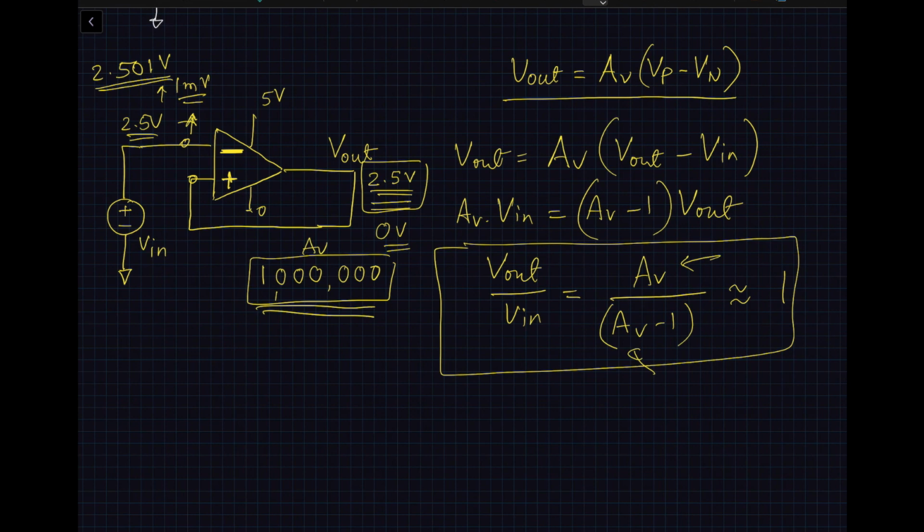And the positive feedback generally, in the amplification type of situation, is not a good thing, because it would latch up the system one way or the other. And in the speaker and microphone example that I gave you, it won't latch up. You will just hear a really loud tone, which is the other mode of operation of the amplifier, which is like an oscillator. Okay, we are going to touch upon that later on. Coming back to this particular example, this is an example of a positive feedback.